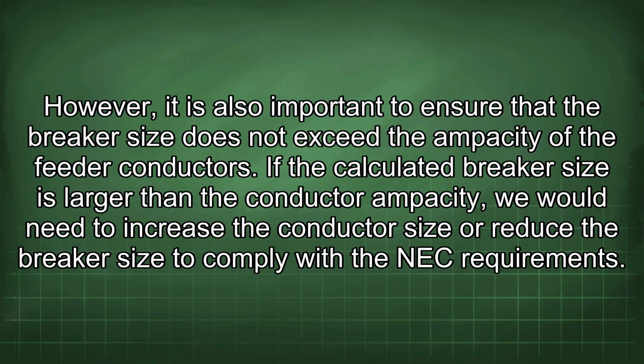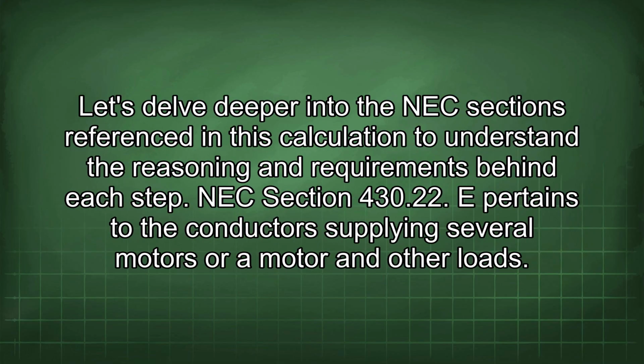However, it is also important to ensure that the breaker size does not exceed the ampacity of the feeder conductors. If the calculated breaker size is larger than the conductor ampacity, we would need to increase the conductor size or reduce the breaker size to comply with the NEC requirements. Let's delve deeper into the NEC sections referenced in this calculation to understand the reasoning and requirements behind each step.